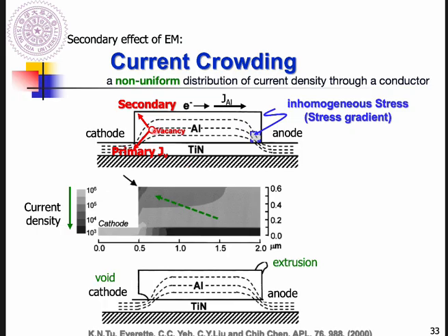But some people will further ask, why, Professor? You can interpret this in terms of vacancies and electron flow. If you have lots of vacancies here, they will impede the electron flow. When electrons flow to the right-hand side, they push the vacancies, because vacancies increase the resistivity.